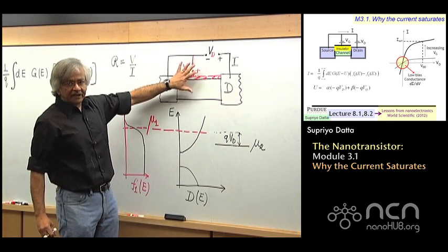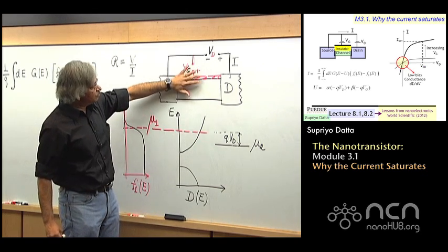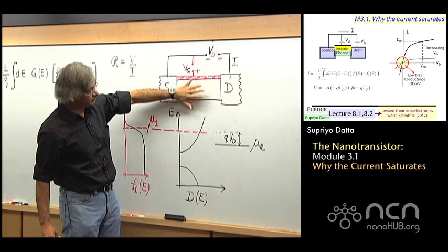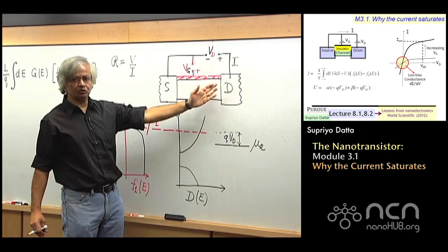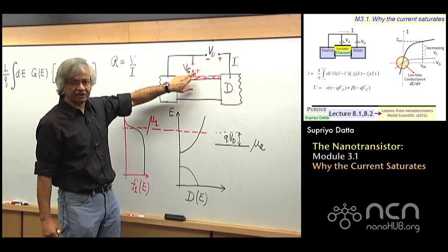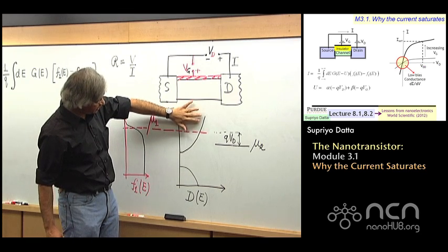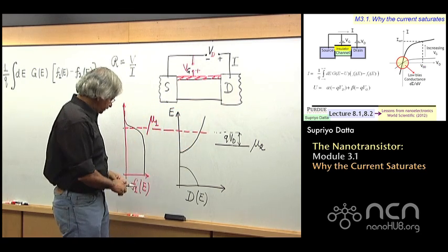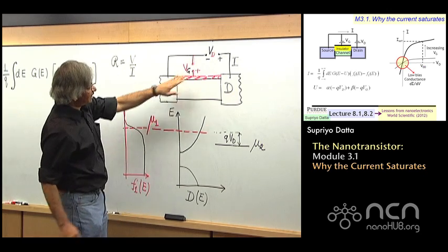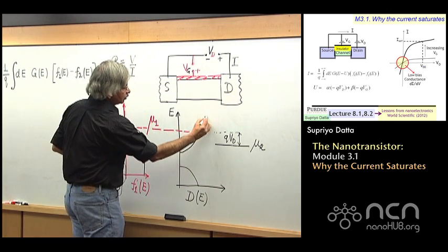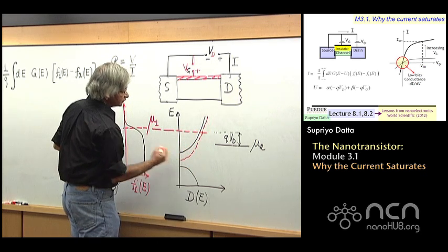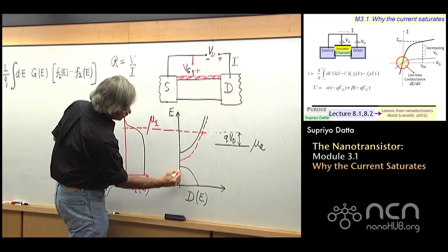Now, the purpose of the gate voltage is to move all the energy levels in this channel region relative to the two contacts. So we could either say that a positive voltage on this moves everything down. So instead of the way I have drawn it currently, if you put a positive voltage there, it could all go down somewhat, for example. And this would also go down.